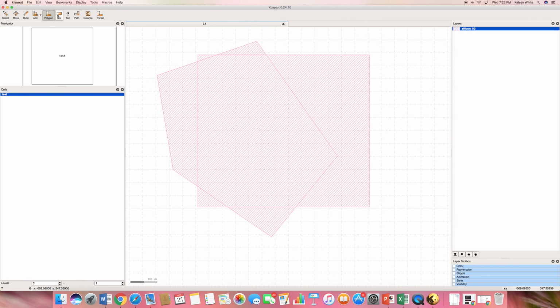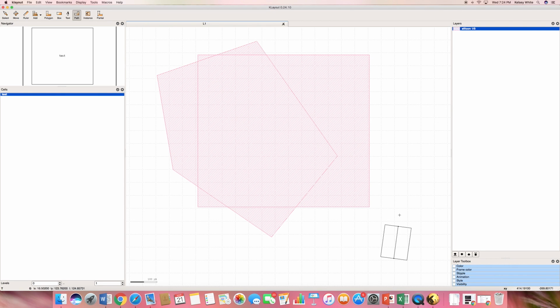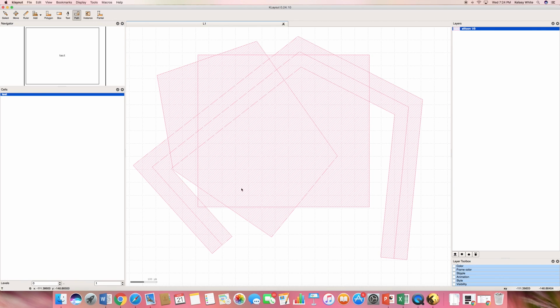The box we've just shown, text isn't too useful. The path bar actually allows you to just define points in your surface, and they have a certain width that you can define. So in this case, it'll be 100 microns. We can choose sort of the edge types, which is fun to play with, and then we can just draw sort of a path, and it makes a channel for us, whatever that channel might be.